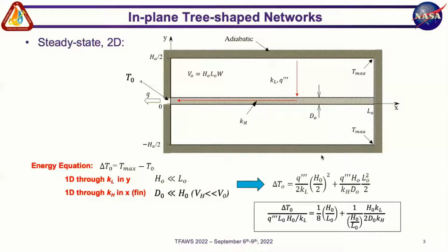Now, we know that if we don't have this high conductivity material that you can place right here in the bottom as shown, this material, as it generates thermal energy in the volume, and you have only 1 point absorption of heat at a certain temperature T0, let's say, here is where the heat generation will escape. After a certain time, when the system achieves a steady state, you find maximum temperatures right here on these opposite corners, on the opposite side of your heat sink, right?